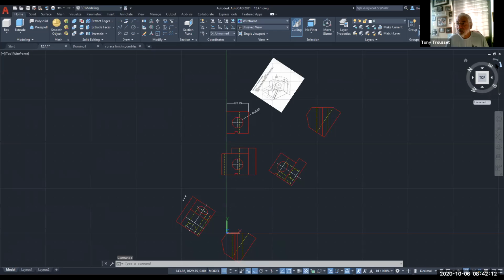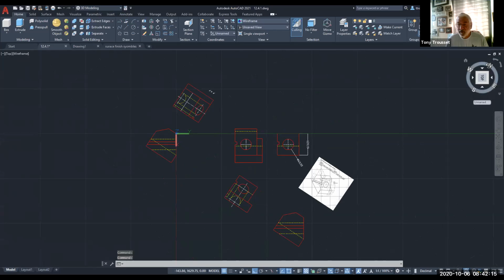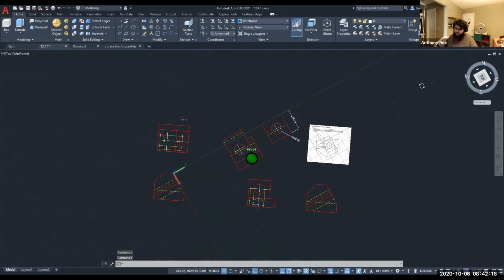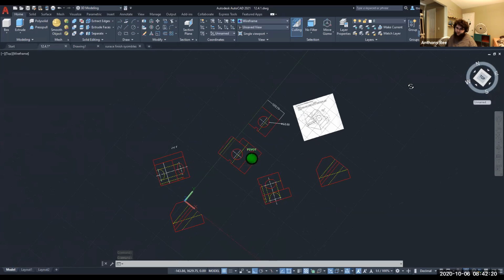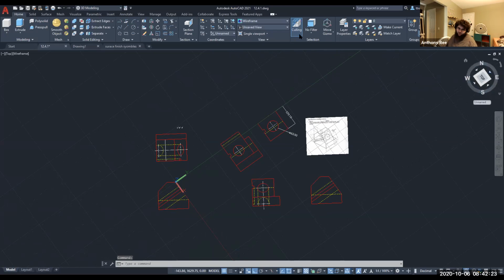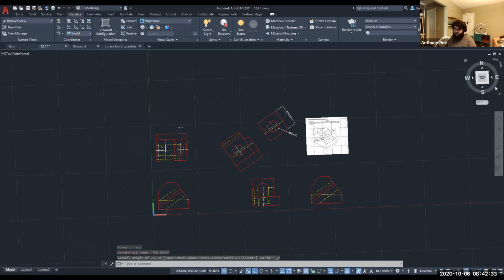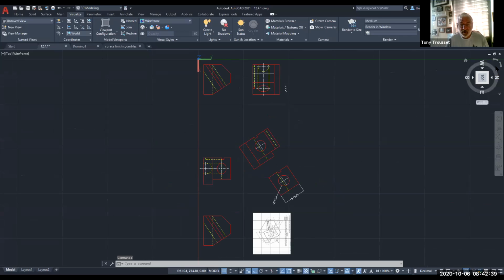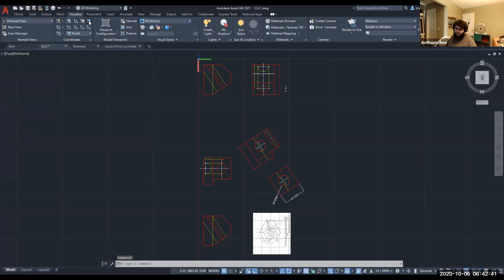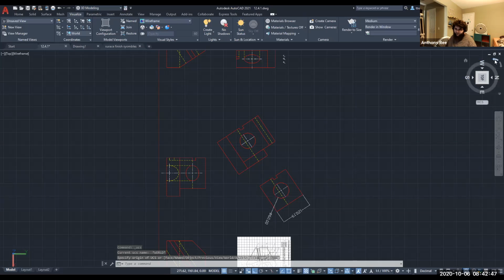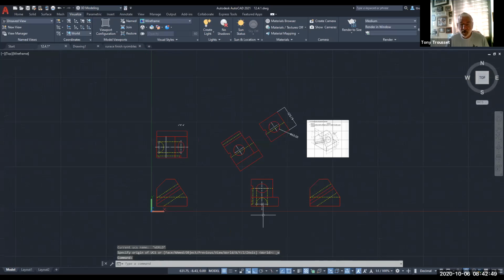No. Try just changing the UCS back to the default or something. That'll probably set it so that the rotation goes back to normal. Yeah, you're right. I'm going to go here to visualize, and then I'm going to go to previous. Maybe that's it. Okay, and then hit like top home or something. Oh yeah, see, now I've really screwed things up. Oh, just rotate it left with the cube. Rotate it left. Yeah, there we go.